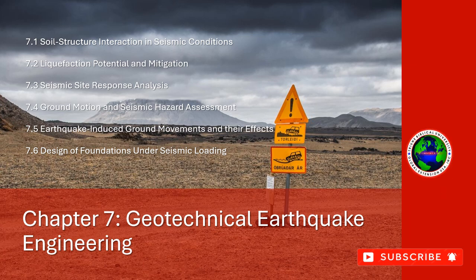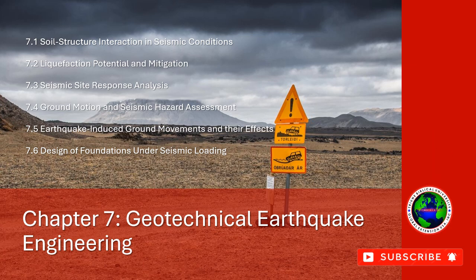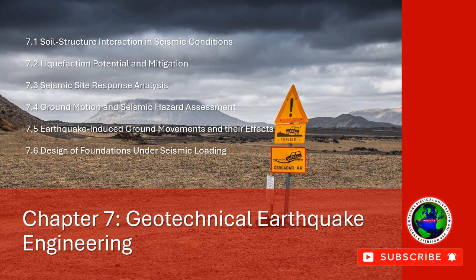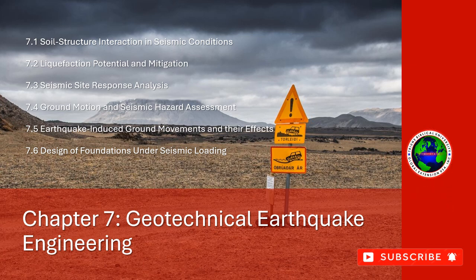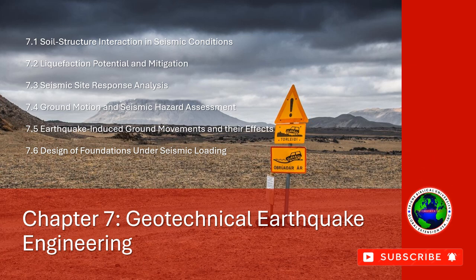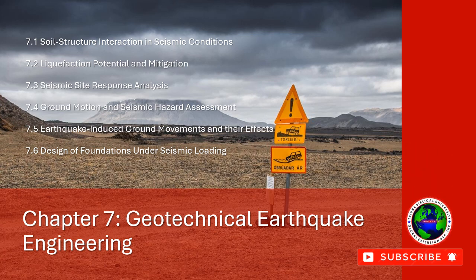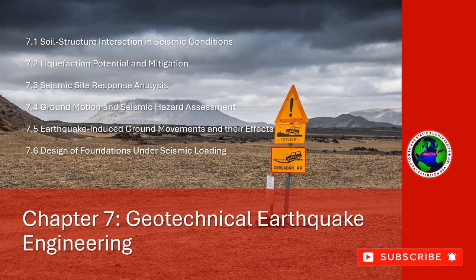The interaction between these waves and the foundation can modify the response of the structure. Inertial interaction. The inertia of the structure, its resistance to motion, influences the interaction with the soil during seismic events. A heavier structure may impose greater forces on the foundation, while a lighter structure may exhibit different dynamic responses.